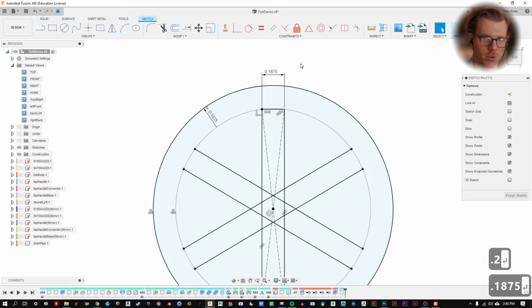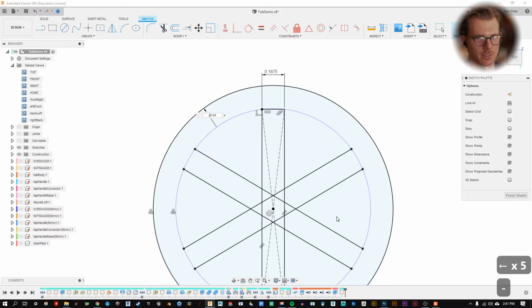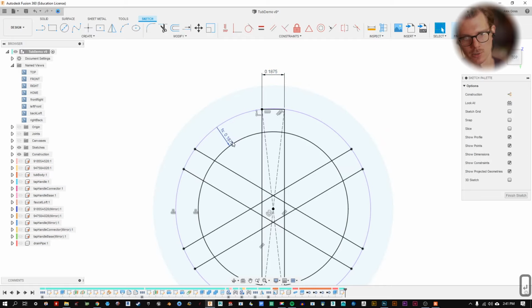However, we want it to go on the inside, not the outside. So there's just a little bit of algebra. Sorry. Double click on that to change it. I'm going to navigate to the far left and just lead that with a negative. So we're saying the offset is negative dimension 104. Dimension 104 right now is positive, so if we make a positive negative, it's negative. Now it's going towards the inside. Beautiful. And now these are parametric to each other, so if we make this something else,